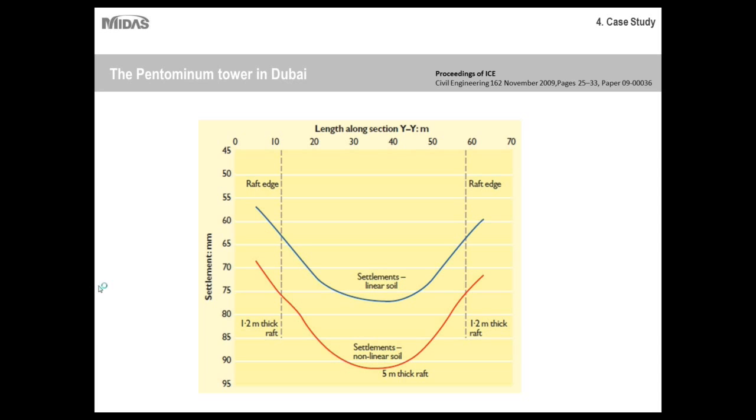So that's one of the main things that I want you guys to get from this presentation in general, that through numerical modeling you'll be able to find more cost-effective solutions. For larger scale projects, it becomes more and more important to take design costs into account. For example, by cutting down maybe a number of piles or using a certain type of element over another, you could save hundreds of thousands of dollars just because you took the time to do a parametric study instead of going with a more conservative design. So just keep in mind that numerical modeling is not only useful in the calculating sense, or the physical sense of calculating your results, but also in the economic sense as well.